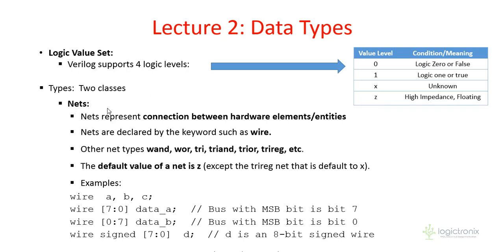And nets, actually nets stands for wires. Basically we use the wire keyword. So wire is for defining any sort of connecting points or connecting jumpers. Like in physical connection we use jumpers, wire is the jumper for a Verilog program. So wire can be a single bit or multi-bit type of wire, and the size of wire is defined here. So there is MSB down to LSB and the variable name. So data underscore A is a wire of 8-bit. So this is the basics of nets.